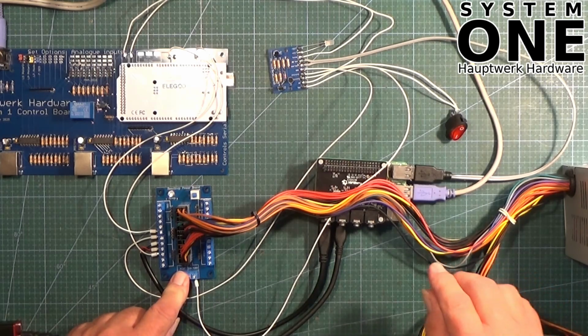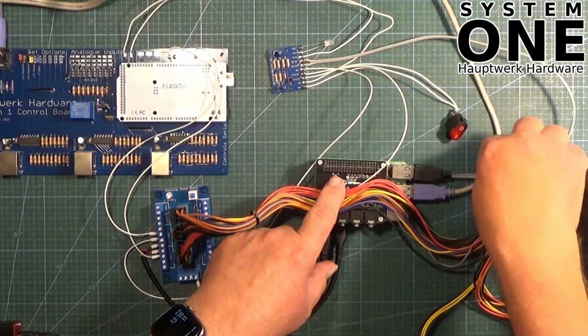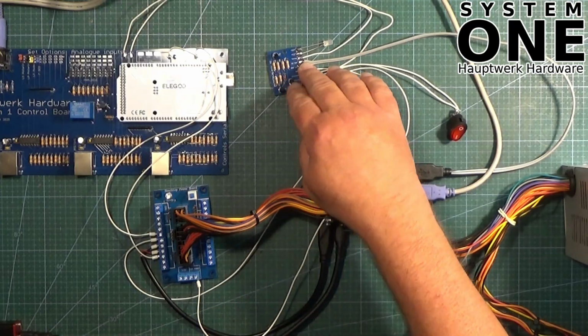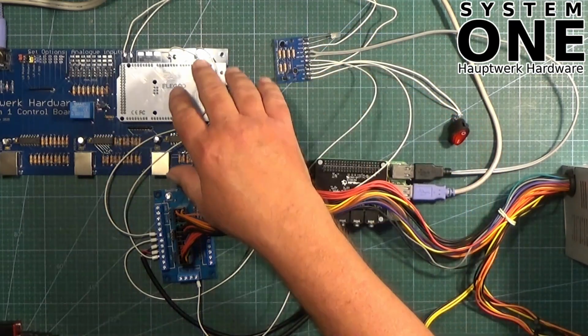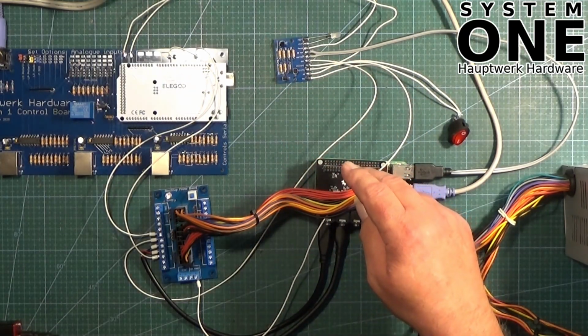And that's pretty much all that we've got there. We'll come on to this cable in a second. This other USB connector, the black one from the back of the Raspberry Pi, comes round to our power management system, and the reason that's there is so that the control board, via the power management board, knows all the while that the Raspberry Pi is powered up.